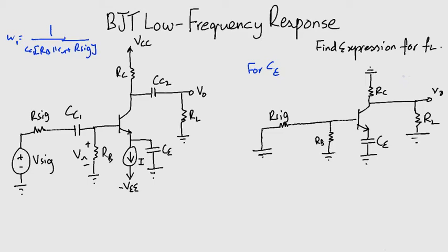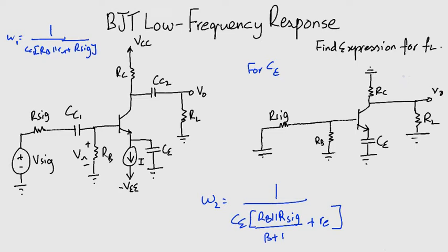What we can do is reflect the base resistance network into the emitter side. Let me show you how. Instead of multiplying Re with beta plus 1, we divided Rb parallel with Rsig by beta plus 1. Obviously, if we had reflected the emitter onto the base, we would have gotten equivalent results.